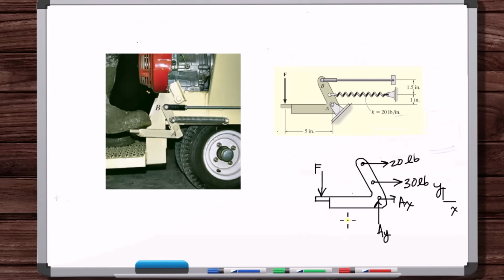Now, if you notice, the free body diagram we just did was a special case. This is a planar free body diagram, right? This is in 2 dimensions. So what are the requirements of the system that allow you to do a planar free body diagram? Well, if all of the forces are coplanar. No, that's not the requirement. In fact, the forces don't have to be coplanar. The requirement is that the geometry of the body that you want to make a free body diagram of needs to have a plane of symmetry through its center axis.